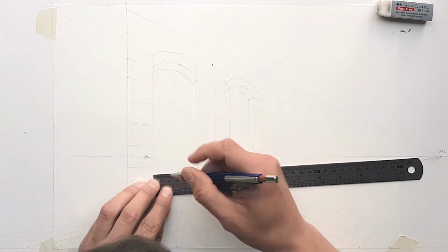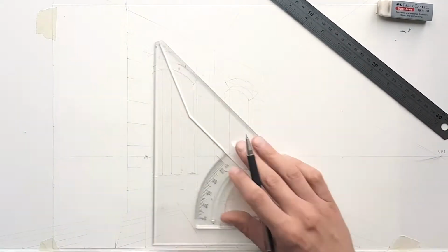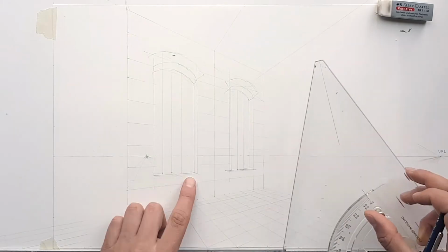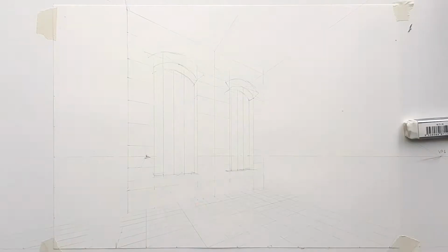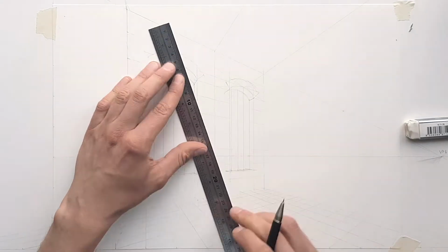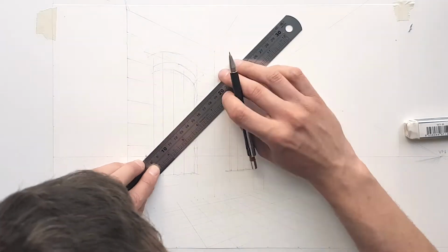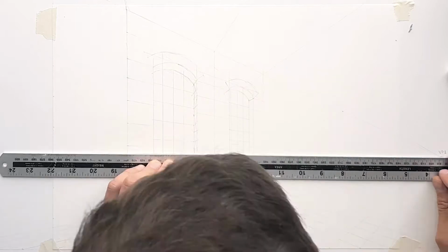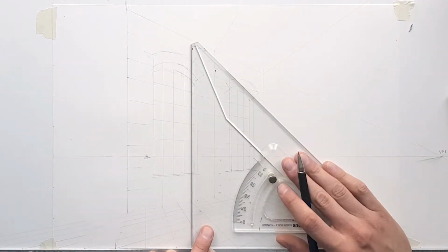So you'll notice for the next step, the sill is divided into 4 equal increments. Strictly speaking, a perspective method probably would have been better, but the distortion on that back wall is so small that it doesn't really matter in this case, so I'm just using a ruler to divide the sill into 4 equal parts. To get the transom spacing at half a meter distance from the sill, I've divided each spacing into 2 using this cross method. I cannot just use the back wall divisions as guides because the sill itself, as you remember previously, is 1.5 increments from the ground plane.